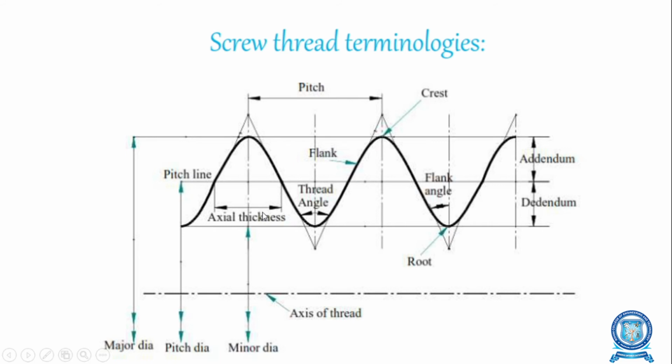Then what is meant by lead? Lead is the distance a screw thread advances in one turn. Here we calculate lead as number of starts into pitch.